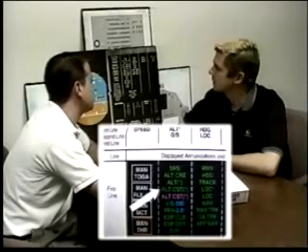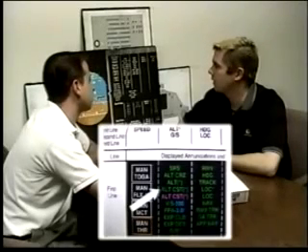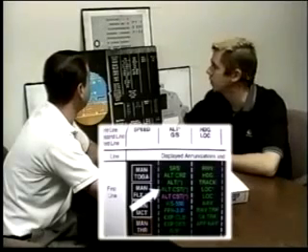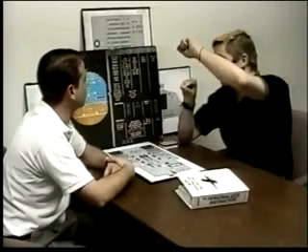Alt constraint. Alt constraint is rarely seen at United. As a matter of fact, it shouldn't be seen at United because we have a policy of setting the most restrictive altitude in the FCU window. But to talk about altitude constraint, this is used during a VNAV climb or descent. And let's just talk about climb mode, because it's just an easy one to start with. If I'm at 5,000 feet and I have a constraint at a waypoint of 10,000 feet, but I go and select 15,000 feet in my FCU window, I'm climbing in climb mode. When I get to the 10,000 feet, it will level at 10,000 feet, and I'll get altitude constraint.